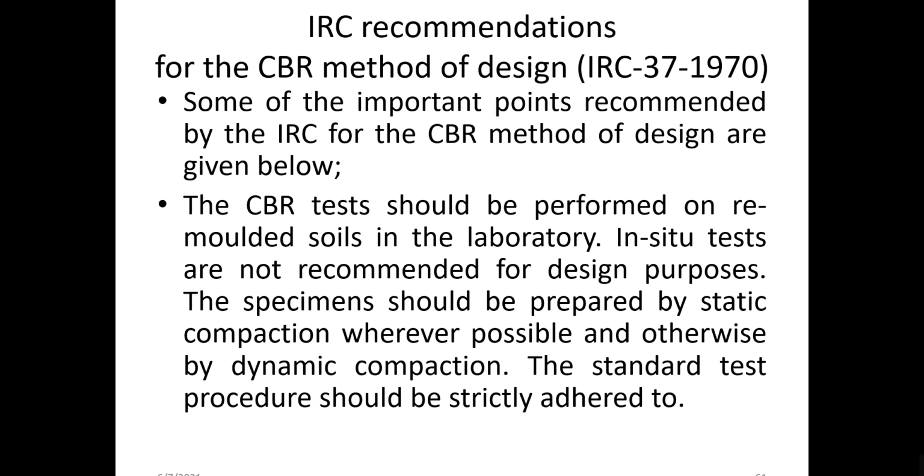For the IRC recommendations for the CBR method of design, we are referring to the old method, that is IRC 37 1970. Here are some of the important points recommended by the IRC for the CBR method design curves. CBR tests should be performed on remolded soils in the laboratory. What do you mean by remolded soils? We collect the soil mass from the site by digging the earth at a suitable depth, say 3 feet, or whatever the depth at which the subgrade soil is going to be obtained. We core cut and get the remolded soil in the laboratory.